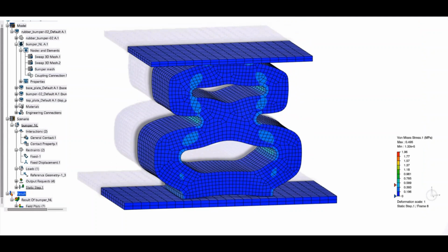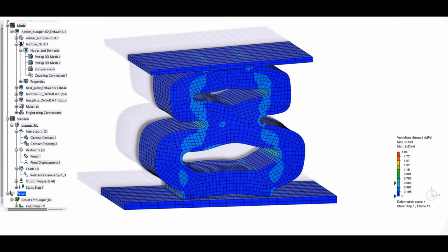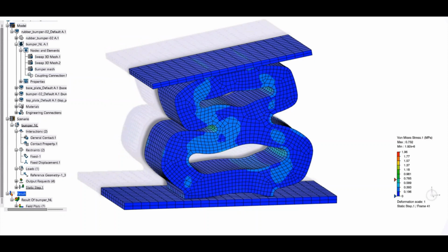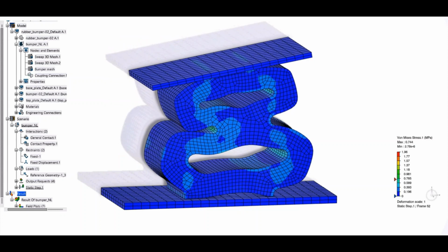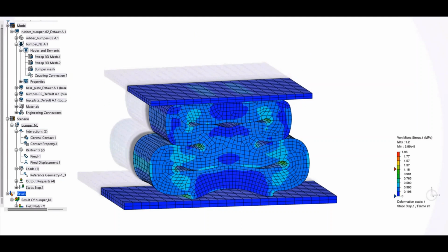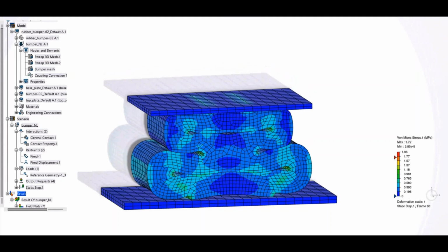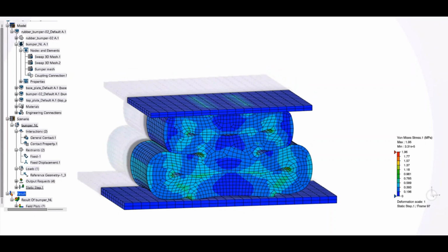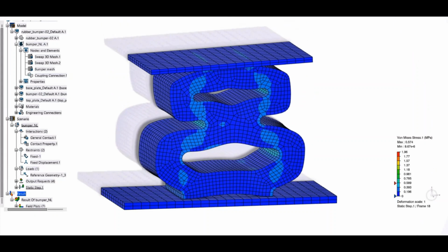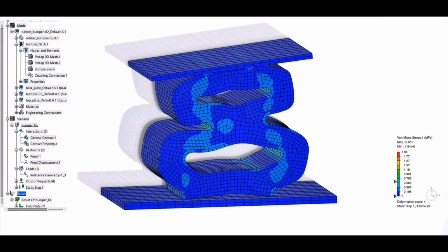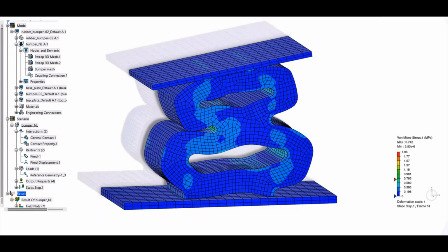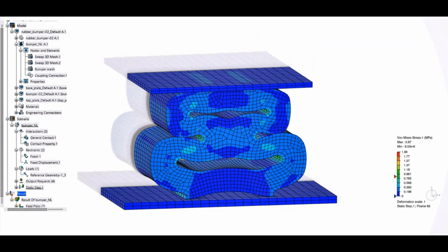Also, I provided a more complex situation because I removed some of the boundary conditions. And here you can see that it's no longer symmetrical, and on the base you can see the face is no longer retained. So you can see one portion that is lifting on one side, and then there is a self-contact that is stabilizing the part.